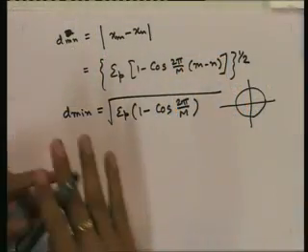So, we have seen for the PSK modulation scheme that the constellation of the modulated signal lies on a circle. Now we will start another modulation technique called quadrature amplitude modulation. This can be said to be a joint modulation of 2 different carrier signals. PAM was just amplitude modulation of one particular carrier signal. This can be said to be joint modulation of 2 different carrier signals.